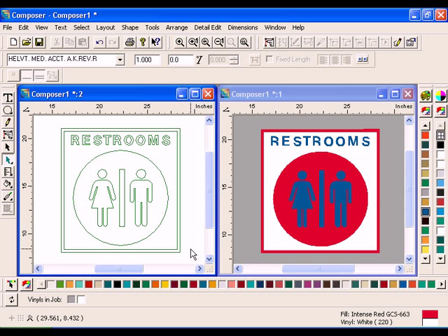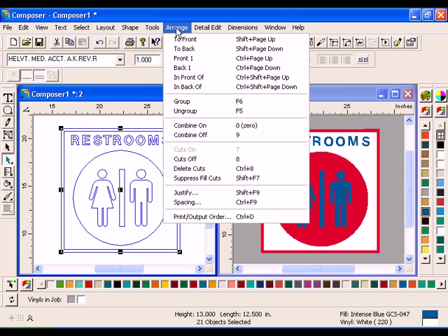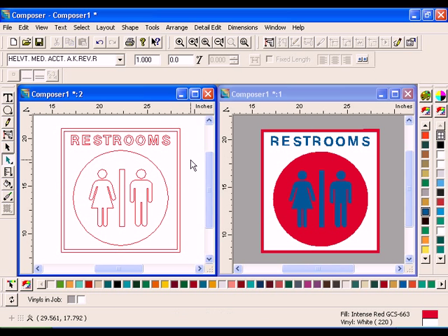When nothing is selected, all shapes appear with green outlines, which means each shape will receive a printed fill color and be cut out. To remove cut lines, first click Select All, then click Arrange Cuts Off. The Wireframe Cut Print Colors window now only shows red lines, meaning print shapes only.